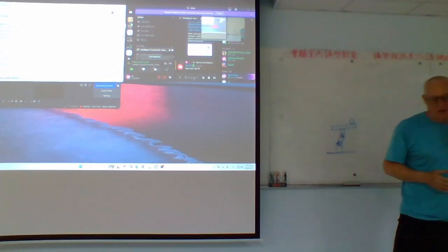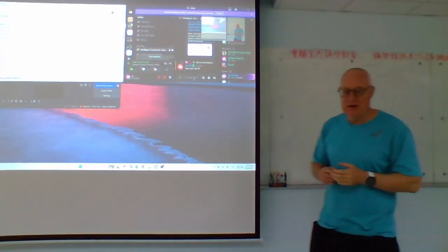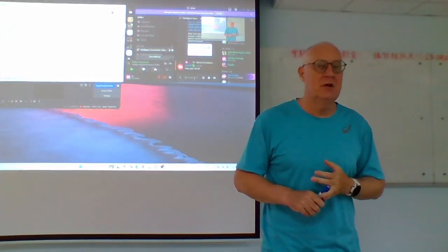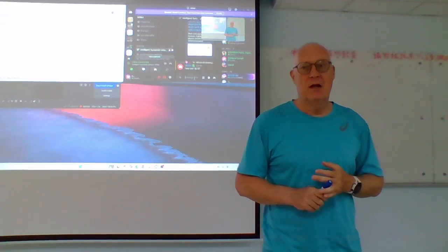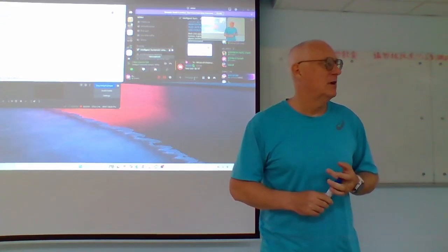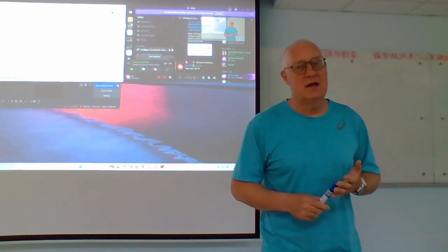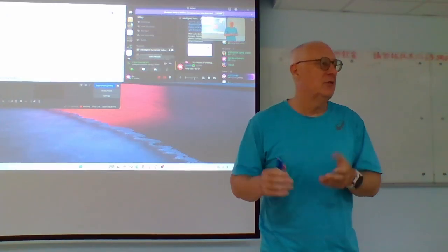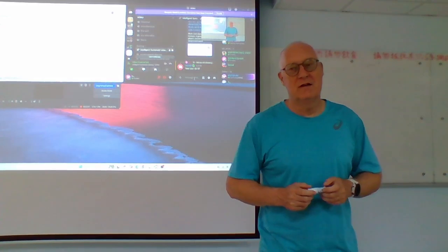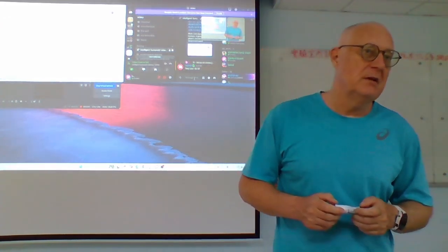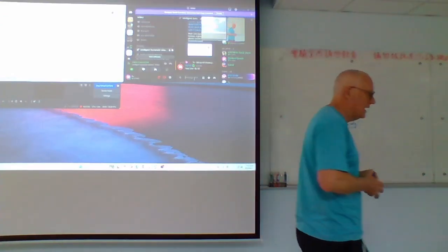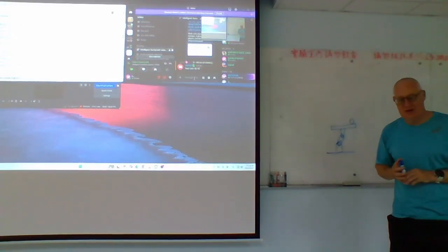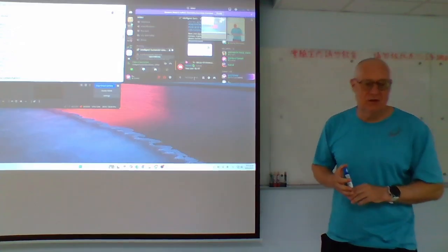The other ones that are popular nowadays are Isaac Sim and Isaac Lab, which is what we're using a lot in our lab. The disadvantage of those is that it's not open source, and you need to have an NVIDIA graphics card. And for the latest version, you need a powerful RTX card in order to run the Isaac Lab stuff. So MuJoCo is quite a bit easier to install.